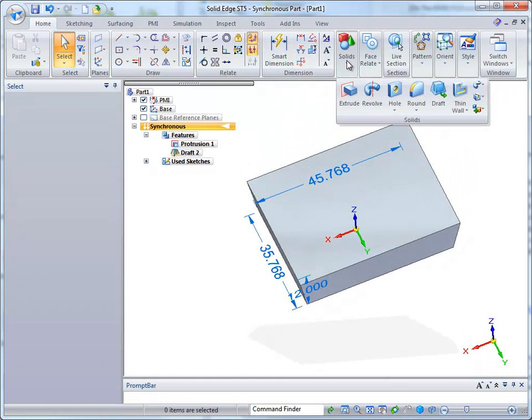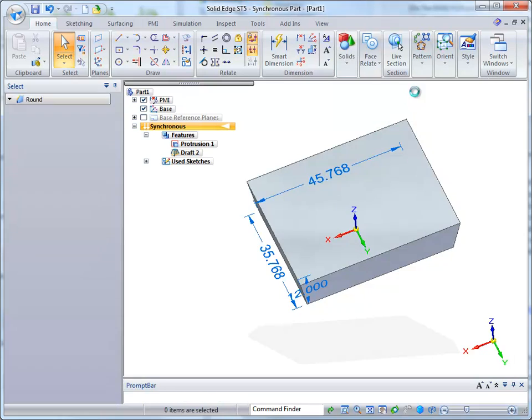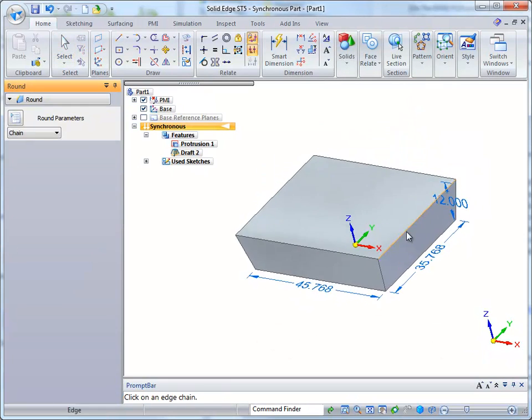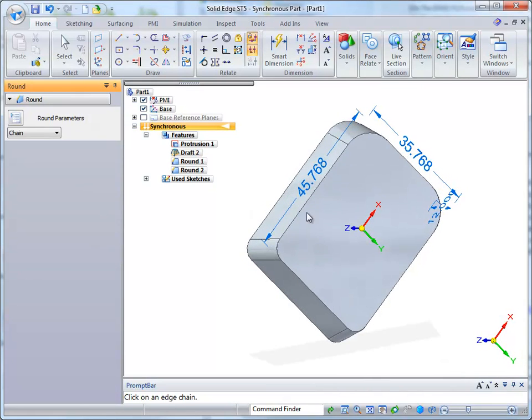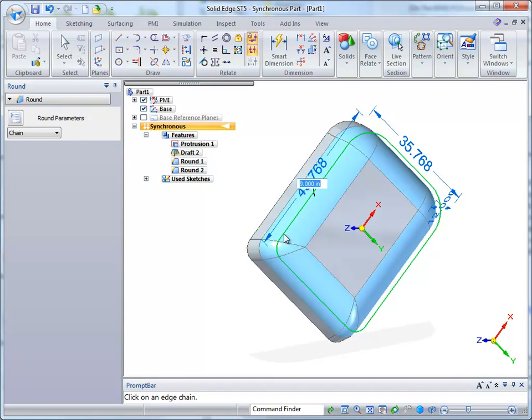And now I'm going to create some fillets for the corners of these things. And fillets are going to be under here for round. And one thing, you can select corners through the solid. Okay, so 4 inches on one end. I'm going to do that. Keep this going again, and bring my cursor over that with a wheel and run that up to, say, 9 inches and hit enter.